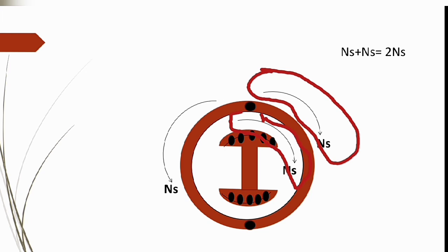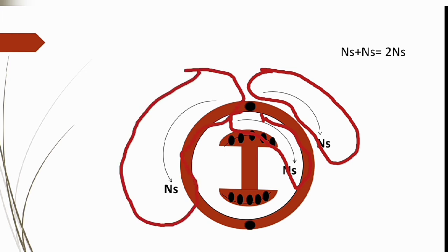Due to the positive phase sequence field, the stator field rotates at synchronous speed in the clockwise direction, and due to the negative phase sequence field, the stator field rotates in the anti-clockwise direction.